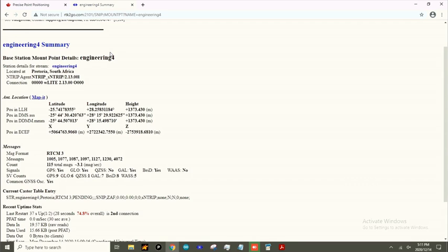And using our LTE 4G connection, we're going to take the stream of data and then push it over a Bluetooth interface into our RTK receiver, where it automatically combines these corrections to provide us with RTK capabilities, getting that 14mm accuracy geolocation service. So see you in the third and final video.